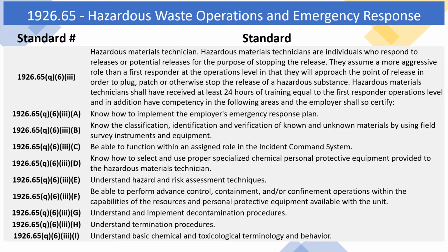1926.65 Q6 3a. Know how to implement the employer's emergency response plan. 3b. Know the classification, identification, and verification of known and unknown materials by using field survey instruments and equipment. 3c. Be able to function within an assigned role in the incident command system.